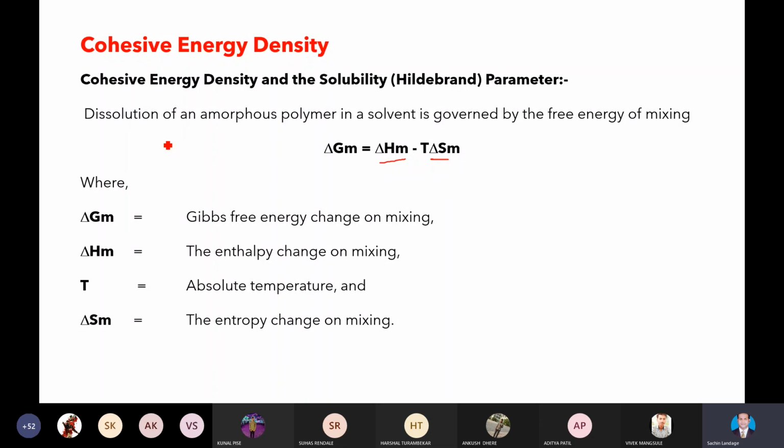Whatever the cohesive energy density is, it is directly proportional to the molecular weight. The cohesive energy density of cotton is 6,200 calories per mole per 5 angstrom chain length, and 70% H2SO4 supplies that much energy to dissociate the bonds existing between the molecules of the cotton fiber, the polymeric chains, which is supported by the Gibbs equation of Gibbs free energy change on mixing.